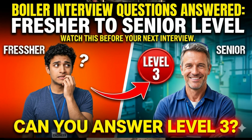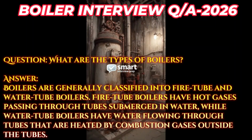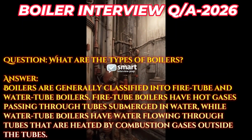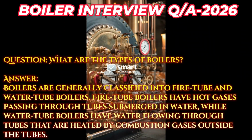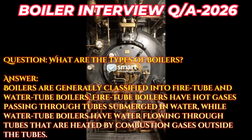Question. What are the types of boilers? Answer. Boilers are generally classified into fire tube and water tube boilers. Fire tube boilers have hot gases passing through tubes submerged in water, while water tube boilers have water flowing through tubes that are heated by combustion gases outside the tubes.